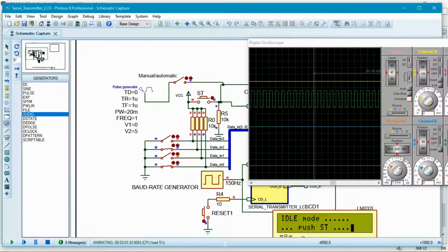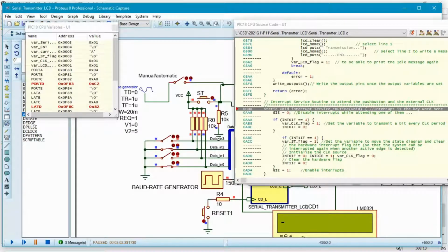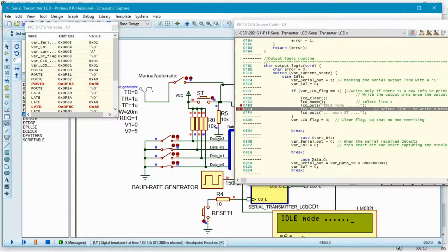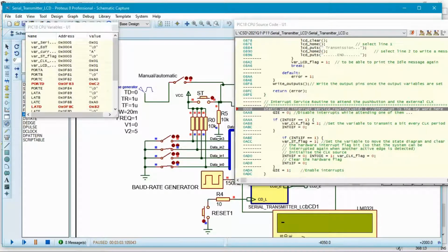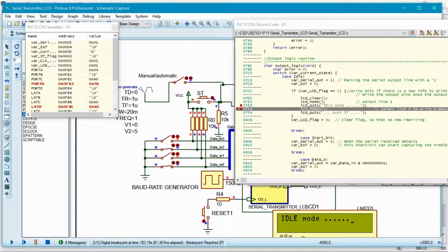So now it's the time when we will stop counting, and you see it's paused, and now let's click. So that's it. You see, I have skipped that. Let me do it again. Click to start the first breakpoint and click the next breakpoint. Now I see that number down there. You see, it takes 81 milliseconds to write this instruction. So this is really a lot of time.